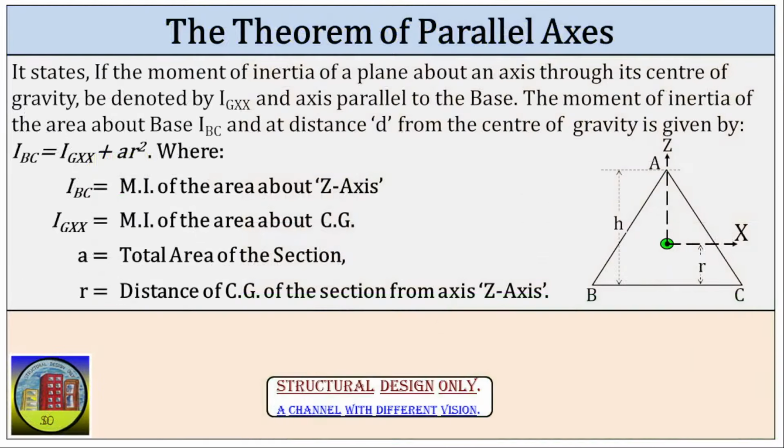The parallel axis theorem. The image illustrates the parallel axis theorem, which is a principle used to calculate the moment of inertia of a planar lamina or flat plate about an axis that is parallel to, but offset from, its center of gravity, CG.